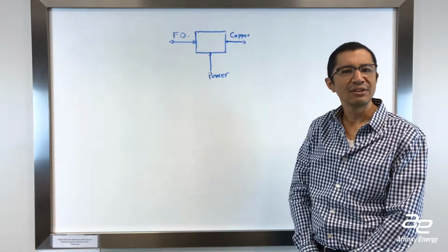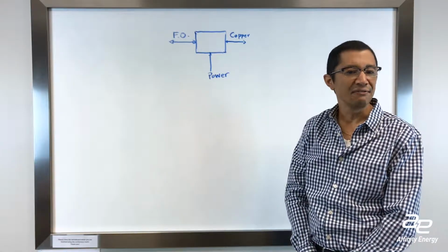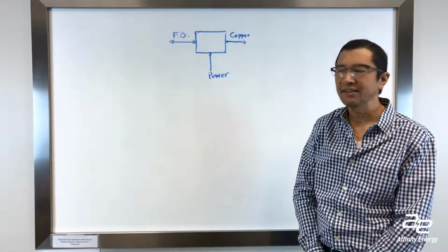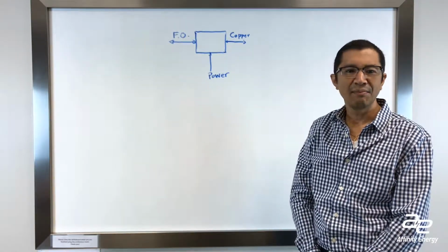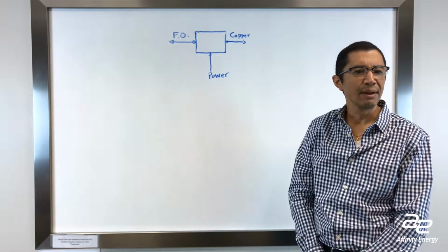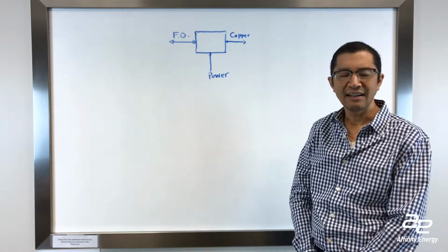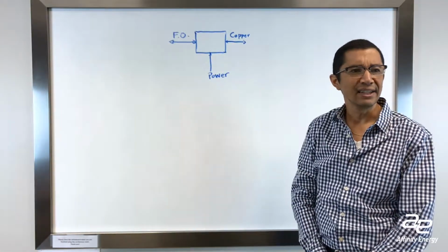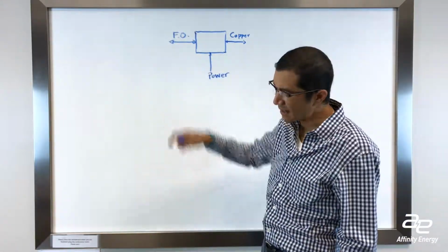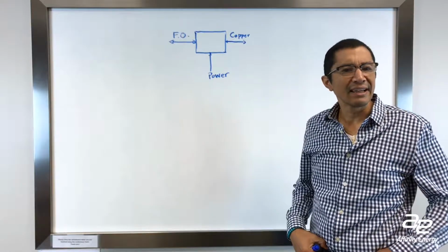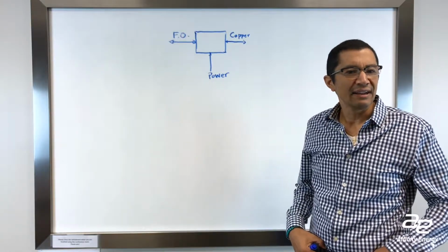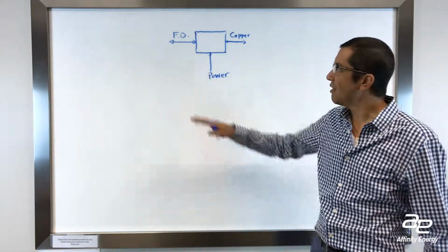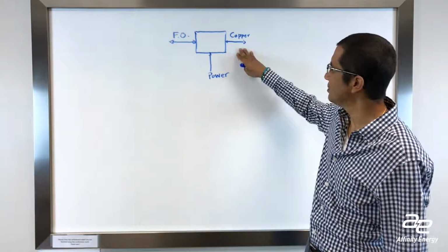The second one would be you're concerned over noise or interference, and this could be electromagnetic interference or it could be radio frequency type interference. But essentially, you're wanting some isolation from potential noise. Maybe you're in a very high electrical environment and therefore want some protection against noise that could occur on your communication lines. The other reason why you might use fiber optic would be you've got an application or a network that requires a lot of bandwidth, or you need to move a lot of data between point A and point B. So fiber optic has a very large capacity compared to copper.